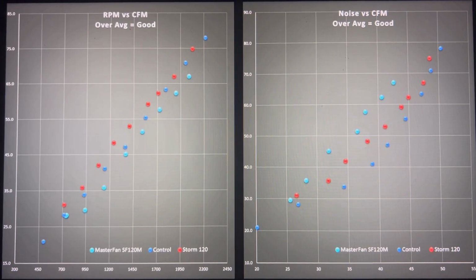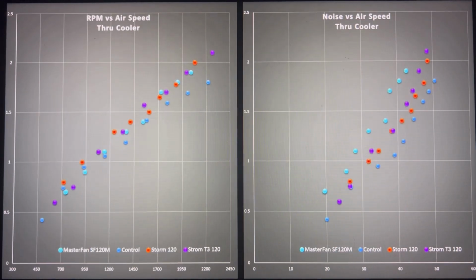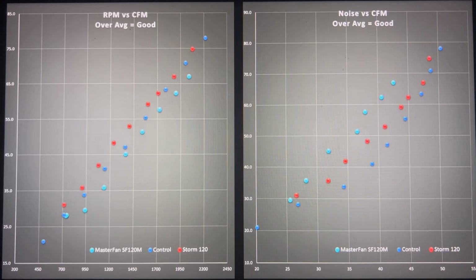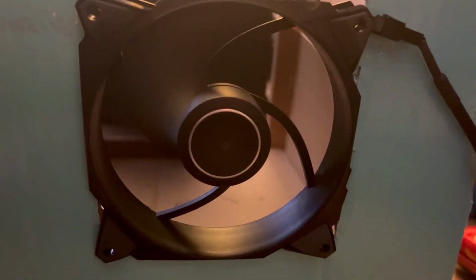I would like to get my hands on a radiator to do additional testing with a thicker, more dense test so that it's much more pressure optimized. But the way you would use these graph data is if you're looking at a smaller form factor case, you want to take a look at the 6-inch mark as well as the performance data through my CPU cooler. Those give trends towards pressure optimization in fans. While if you're just looking at airspeed performance, you want to be looking at the other data points as well as the CFM data.